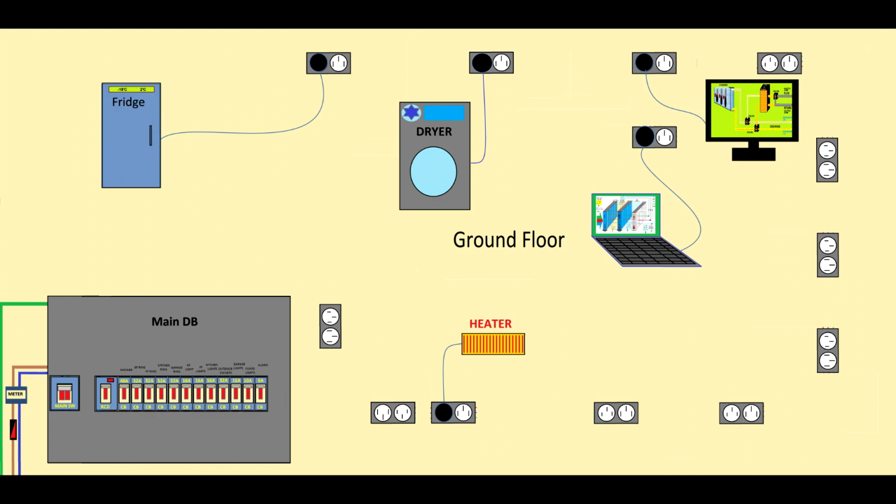Imagine you come from work and your RCD trips, you have an earth leak, and then you will do the basic investigation: go straight to the distribution board, turn off all the circuit breakers and turn on the RCD, and one by one reinstate the circuit breakers. Then you will find the faulty circuit.